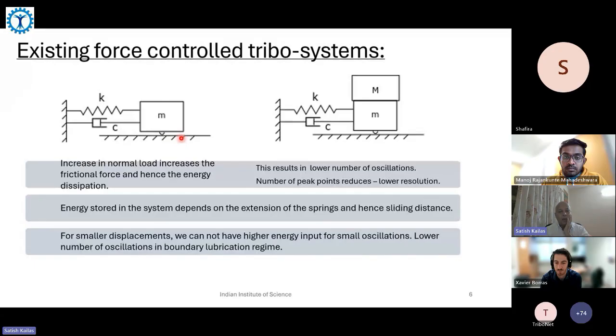So let's say I add a lubricant in between over here. The lubricant will definitely reduce the damping. So depending on the damping reduction, I can kind of predict the behavior of the lubricant. And remember, when it is oscillating, at the ends of the oscillation the velocities become zero. So definitely you move into the boundary lubrication regime.